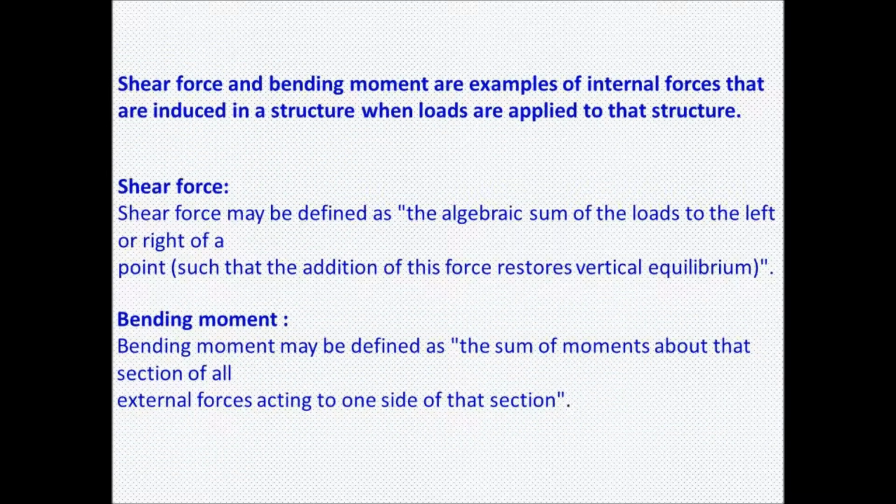Shear force and bending moment are examples of internal forces that are induced in a structure when loads are applied to that structure. Shear force. Shear force may be defined as the algebraic sum of the loads to the left or right of a point, such that the addition of this force restores vertical equilibrium.